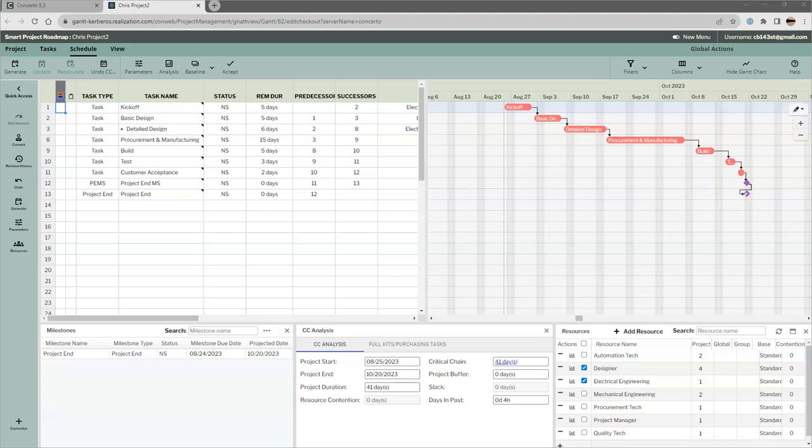Okay, so in this video we have talked about how to add resources to the tasks and the subtasks, and how the roll-up options work for resources. We've run schedule without buffers to check our overall cycle time to see if the cycle time is sufficient or not. We've looked at which resources we might want to level load over. We don't need to level load all of them. We can review the loading graphs to make some decisions, and possibly even accept some small overloads on non-critical resources, as those will work out in execution.